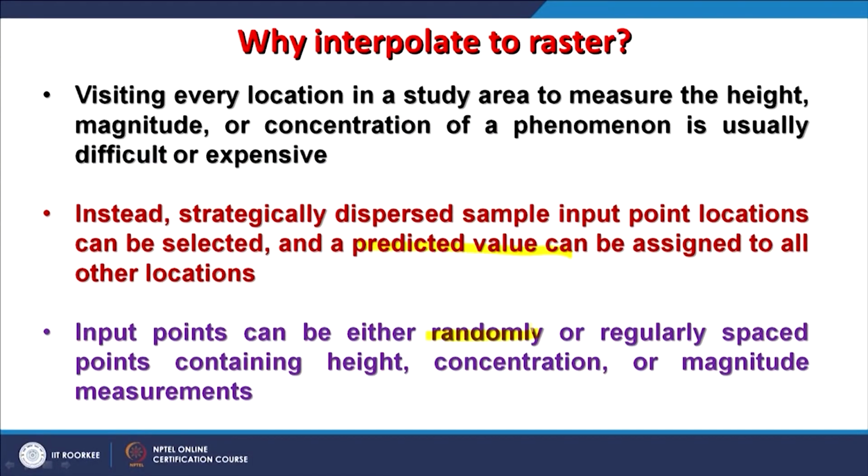Regularly spaced points are near impossible, and if the points, say within one topo sheet, are only located in one corner, these spot heights, and you employ them for spatial interpolation, you may get very poor results regarding accuracy.